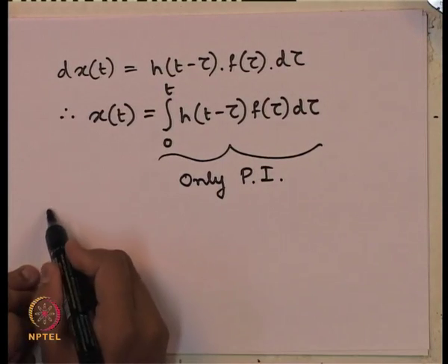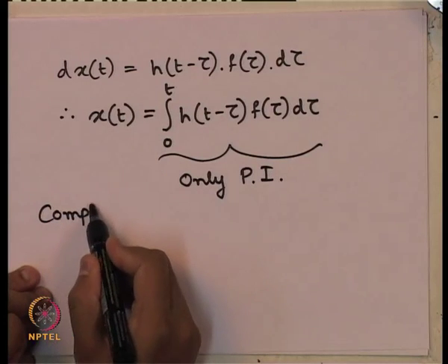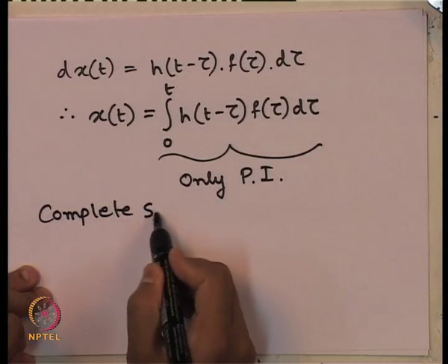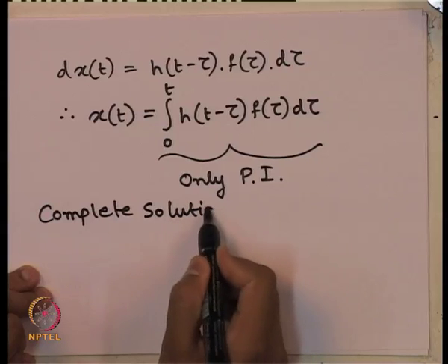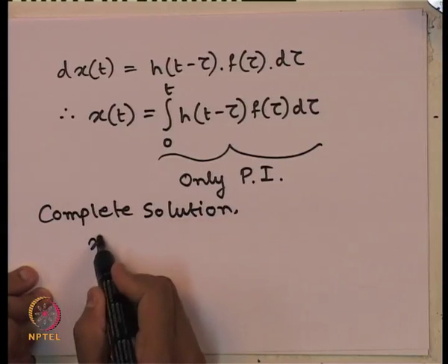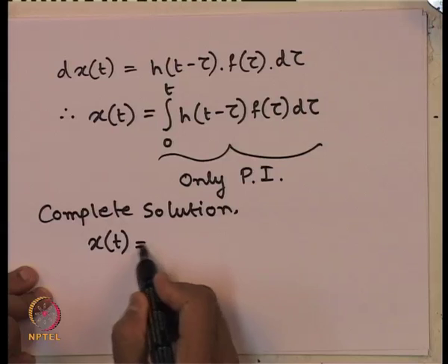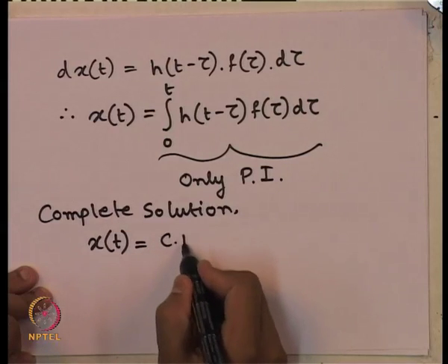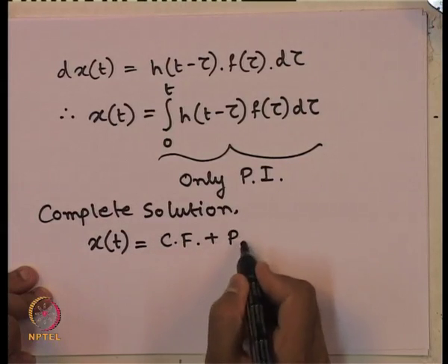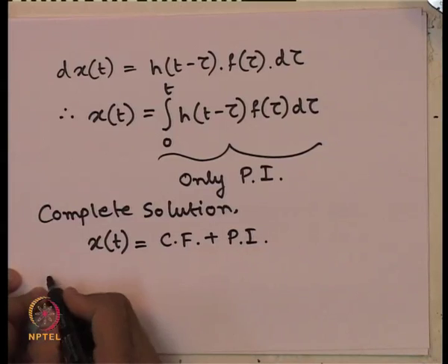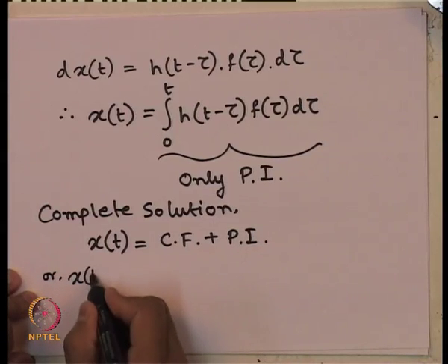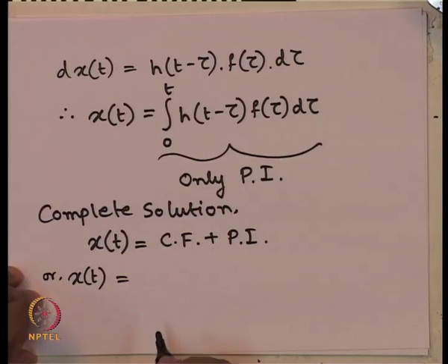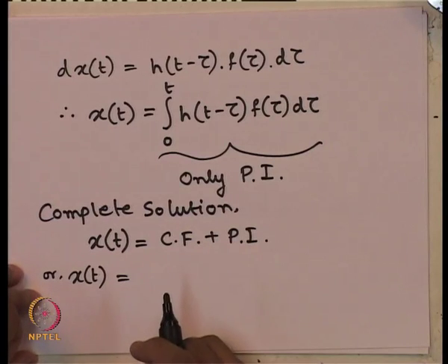So, the complete solution for this problem, that is any system subjected to arbitrary loading, will be complementary function plus particular integral, which is nothing but x of t. Complementary function is similar to the solution for free vibration.